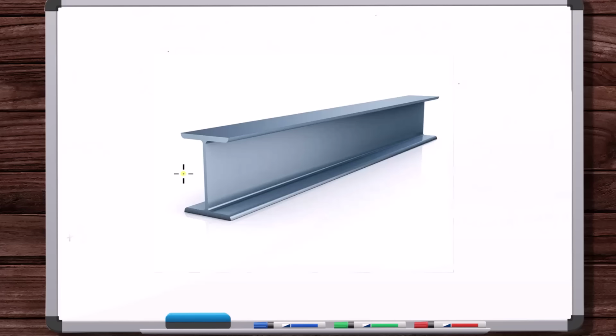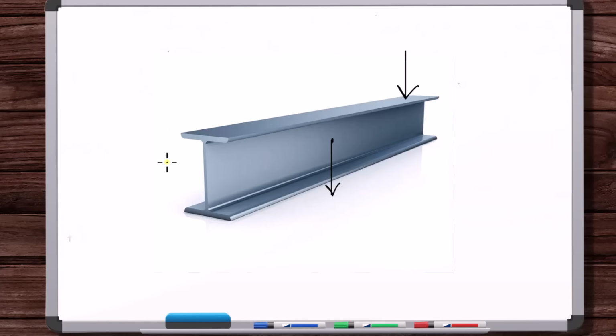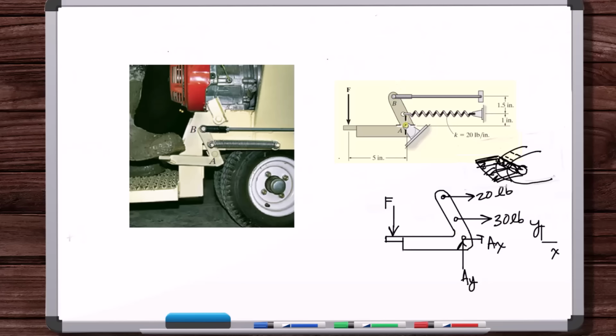Well, okay, the first thing to think about is when we're doing the free body diagram. Actually, let's put the forces back. There we go. So when we're doing a free body diagram and analyzing the contact forces, we find a point of contact, so we know there's a force there. Let's come back here. Here's a point of contact. Here's the link, and we know we have a point of contact here between the pin and the link. The pin's not part of our free body diagram.